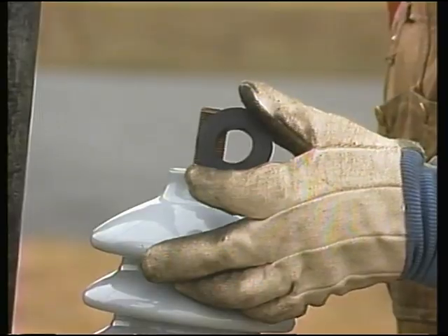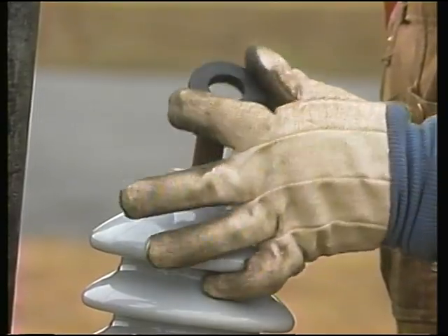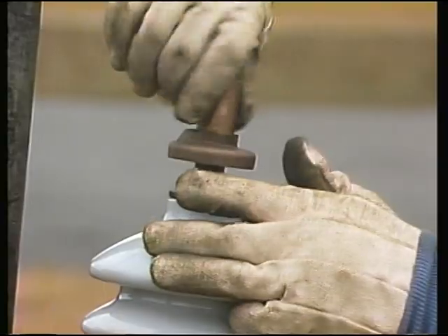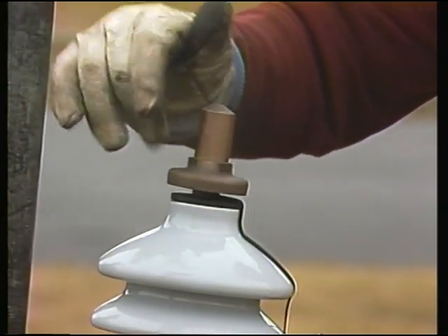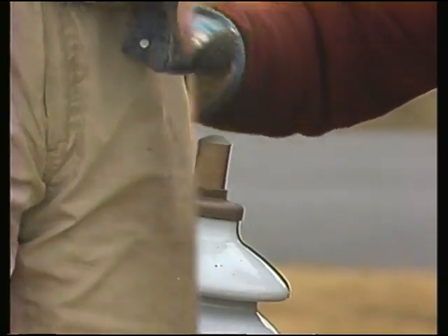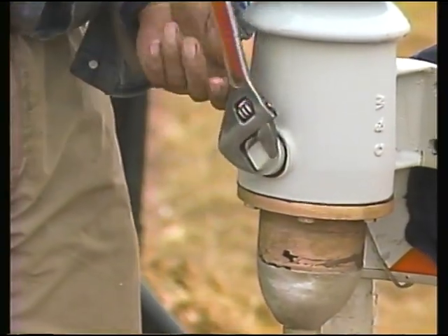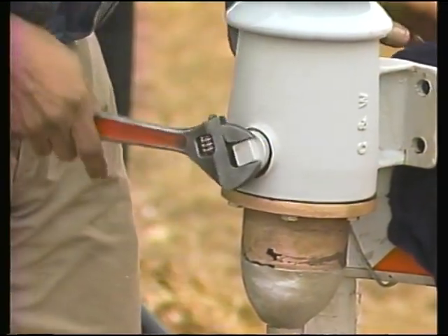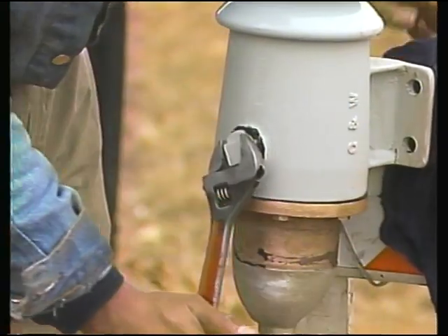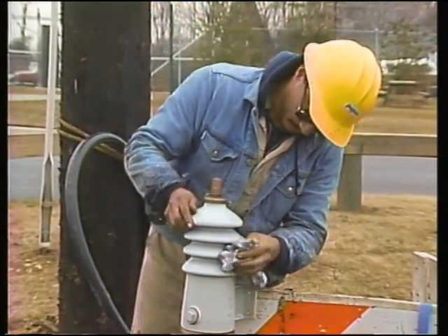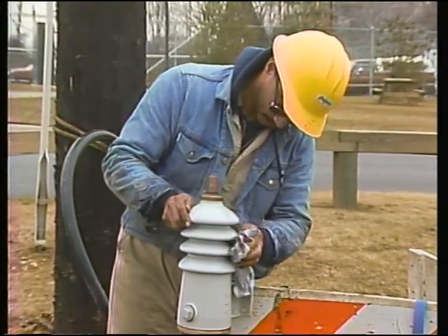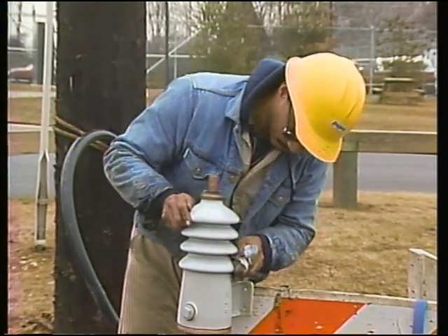Also, while the compound is being poured, occasional heating of the pipe and the connector may be required to keep the compound liquid and to prevent the pipe from clogging. The workman pours in the compound until it reaches the top of the porcelain insulator. Then he tightens the nut on the connector again to keep the compound in the top of the termination. After the termination has cooled, the pipe and funnel assembly are removed and the plug is replaced. Finally, any excess compound that may have accumulated on the porcelain or other parts of the termination is wiped off.